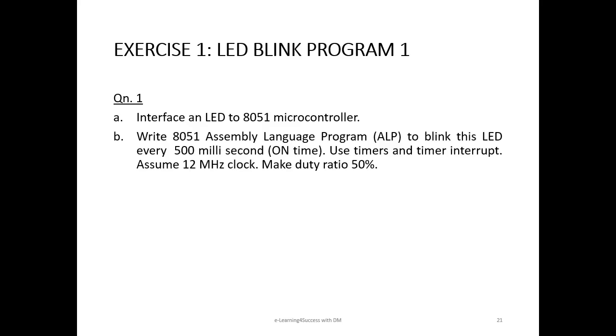Now the first exercise that we are going to do is to interface an LED to the 8051 microcontroller. Then we will write an 8051 assembly language program to blink this LED every 500 milliseconds. The 500 millisecond given should be taken as the LED on duration only. Further, we will assume 12 MHz clock and 50% duty ratio.